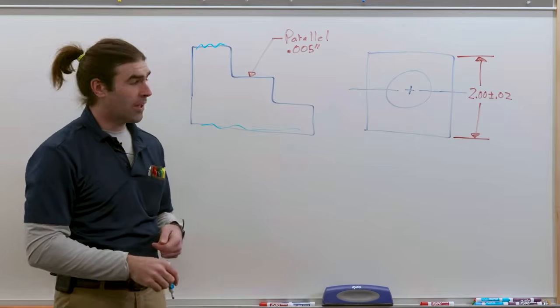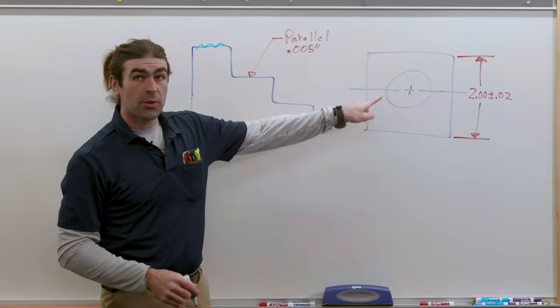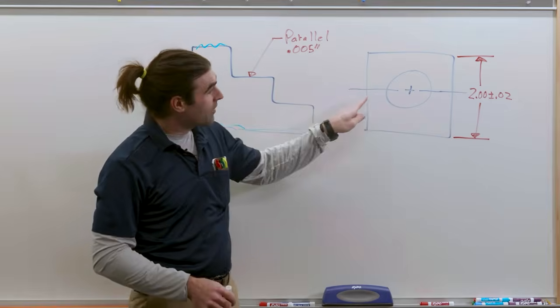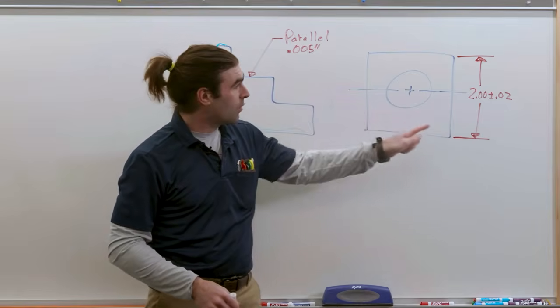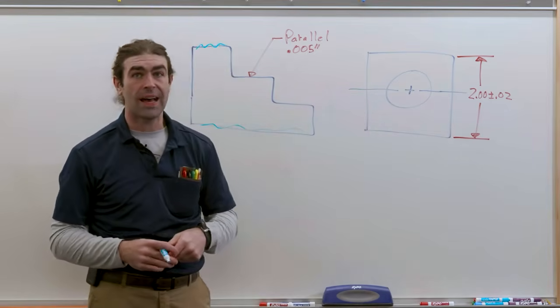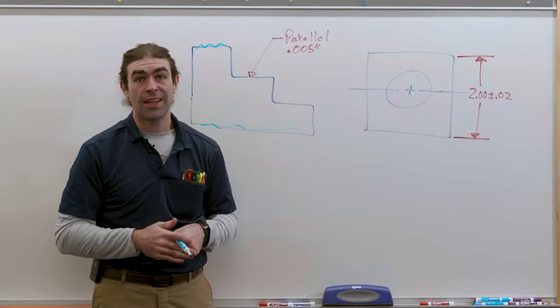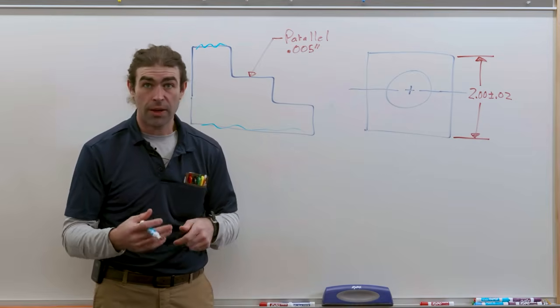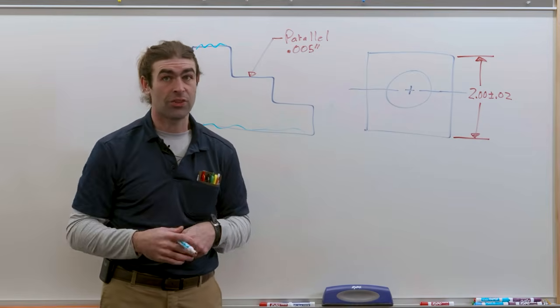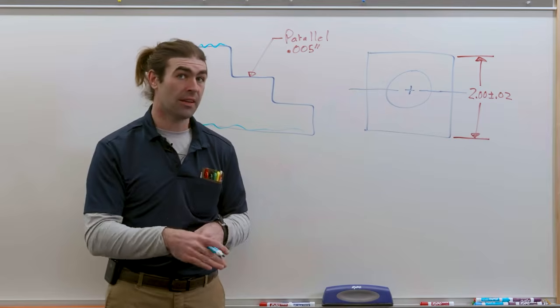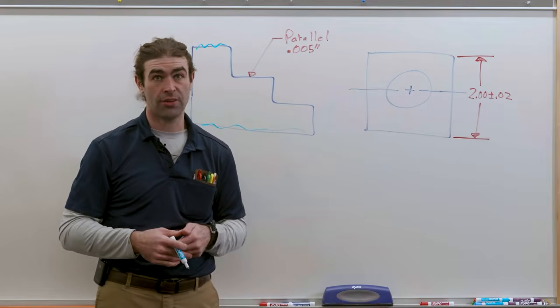Let's go into our next example. We've got a block with a hole in it. Now, we've got a center line going through the block and then 1 dimension covering the height. This indicates that that hole is centered in the middle of the block, okay? So that center line and then that dimension indicates this. We don't need another dimension for the location of that hole.